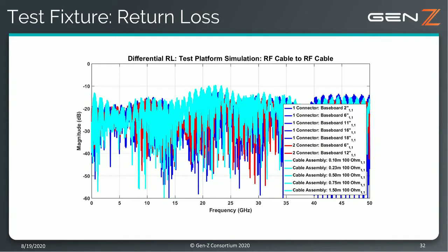One more is the return loss metric that we measured on the platform for all three interfaces. What we really like to see here is that the reflections are not very high. The plot is referenced to 100 ohms and shows that the magnitude of reflections is below 10 dB through really the entire spectrum, where we might have the pathway to 112 gig at 30 gigahertz. It stays below 10 dB and then some to the higher frequencies. So this meets the target, meets the expectation, and we're happy to see that kind of return loss performance.